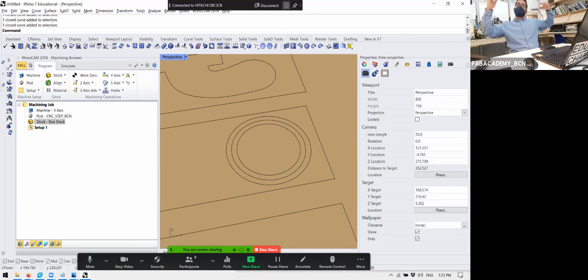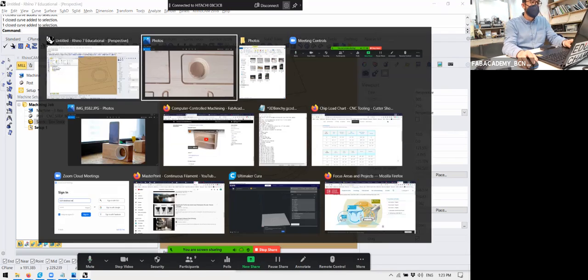So in CNC, it's the same as when reading: we go from the inside to the outside. In CNC, it's inside to outside and top to bottom. We will start from the top layers, the ones that cut less, then the medium ones, then the ones that cut to the bottom, and the same for the outside. So it's always pockets, then in cuts, and then out cuts. What is an in cut and what is an out cut?